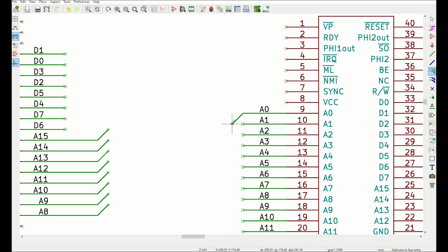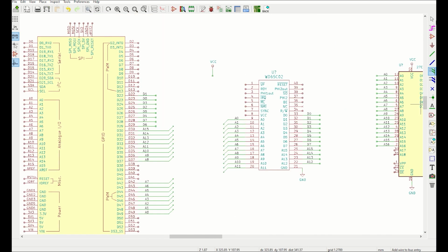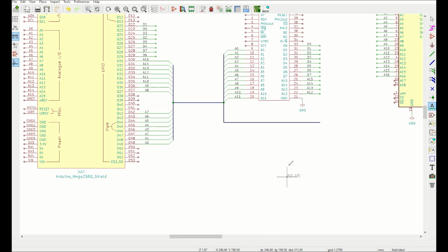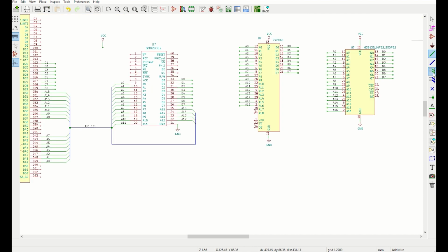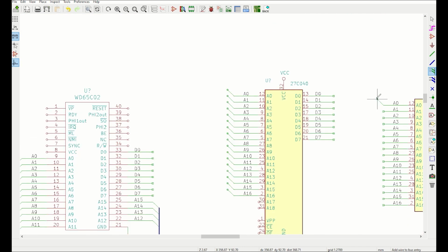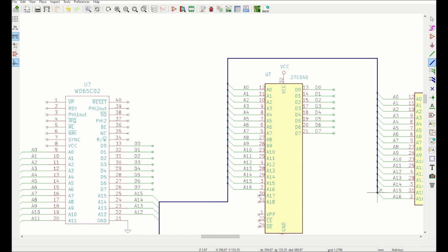And to connect a wire to a bus, we need to use these 45-degree bus connectors. Next, we can lay down the bus, which are these thick blue lines. We then label the bus with the square bracket nomenclature. Here, it's A[0..18]. The reason I'm doing the entire schematic diagram at this stage is so that it makes it clearer how the video circuit's added onto it.